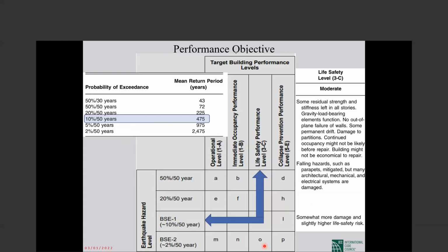Sometimes your performance gets worse, usually better, but you don't have a sense in general. Here you select the level of earthquake and level of performance as if the building is important for you. You want better performance under larger earthquake. You select that, and then you go and check it.